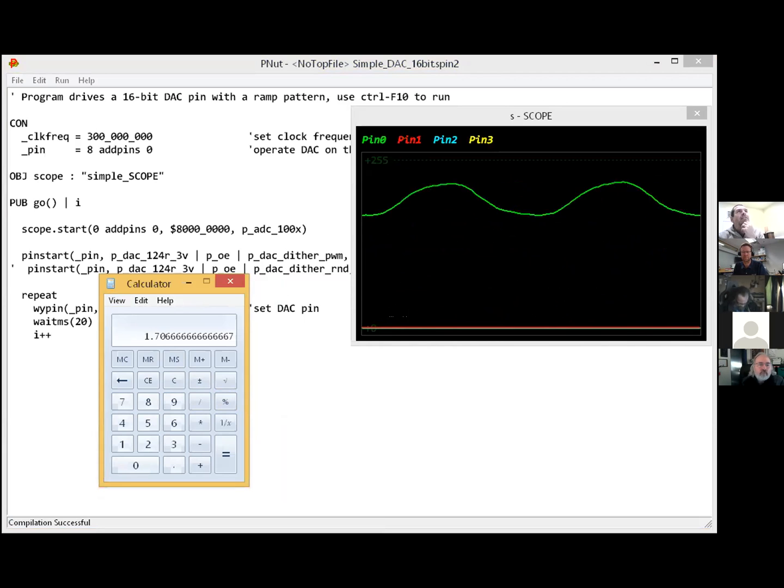That's very fast. Yeah, and it's coming in through ADCs on some other pins, which are filtered with a string of flip-flops. What kind of filter is this? It has curved side lobes. It's making the most of what it can get out of 72 bits that have come out of the Delta Sigma ADC in series. There's a sliding window of 72 bits, and it's filtering them to make these 8-bit samples we see here. In the future, I want to make the ADC faster, and this will sharpen way up. But what we have is actually quite good for audio, and video too, though video is much more demanding.